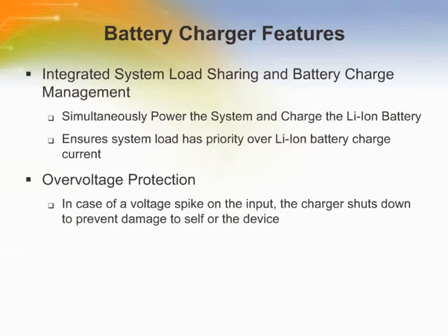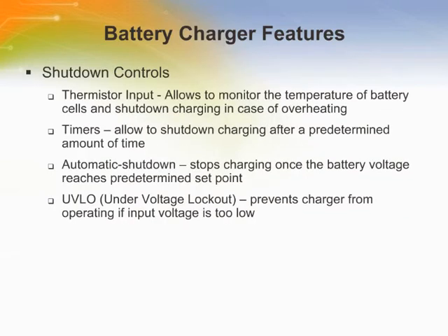In case of voltage spikes on the input, the charger shuts down to prevent damage to self or other devices. In order to supply world-class portable devices, most of Microchip's lithium-ion battery management controllers are equipped with thermoregulation, reverse discharge protection, safety charge timer, and integrated current sensing.